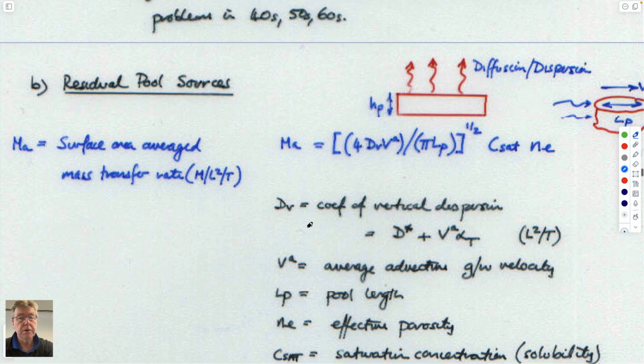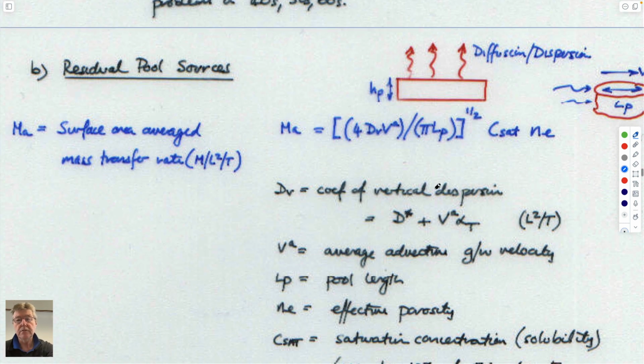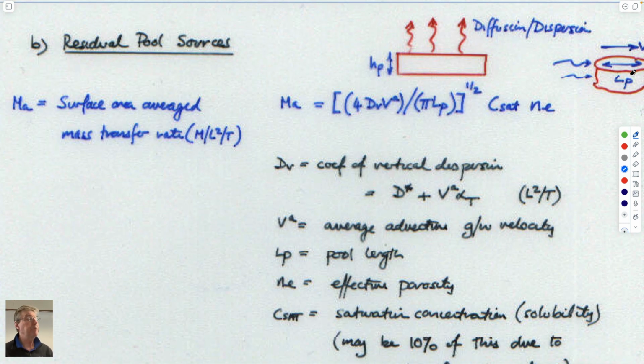And so the other geometry that we might want to use is a geometry that looks like that puddle, a penny that's submerged in the aquifer, that has a height which is HP. P is for the puddle, if you like, this underground puddle. And you can imagine that as water flows past it, maybe just on the top, maybe top and bottom, that this is just diffusing by Fick's law into the flow field, gets picked up by the flow field, and then gets carried downstream.